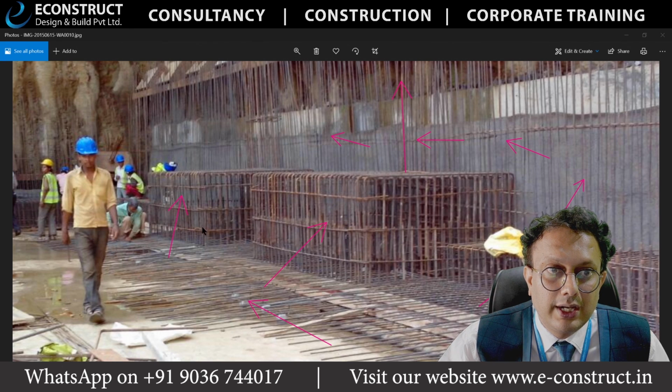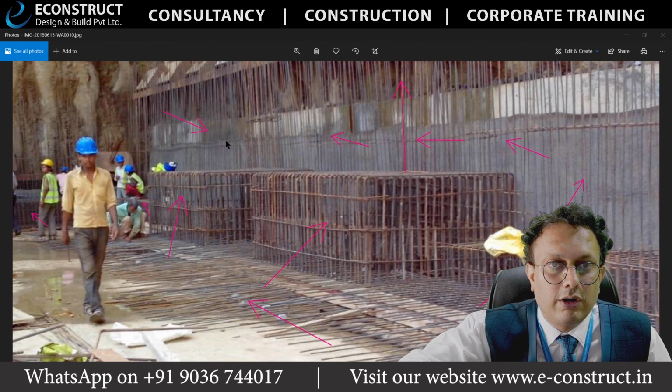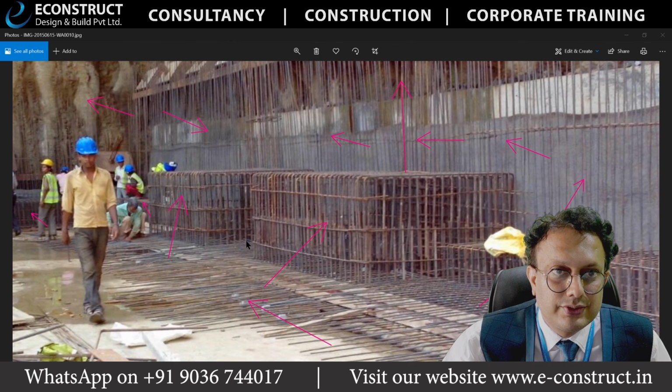This is also the pedestal, and in between the pedestals there is a beam. This is also pedestal. There is a beam here. What is this beam doing? This is basically helping you to transfer the forces taken by the retaining wall. Then what is this? Shoring piles.